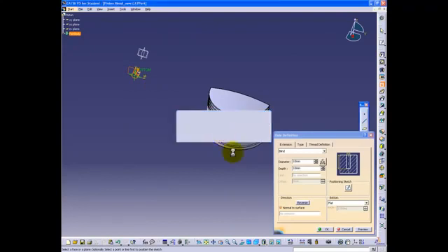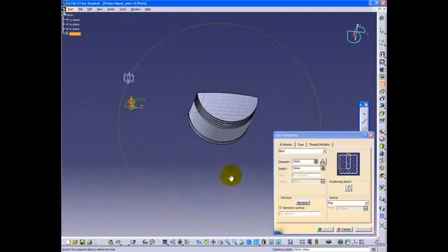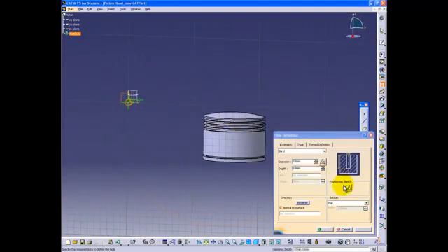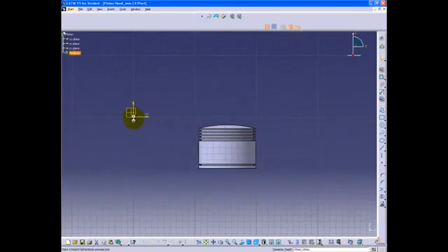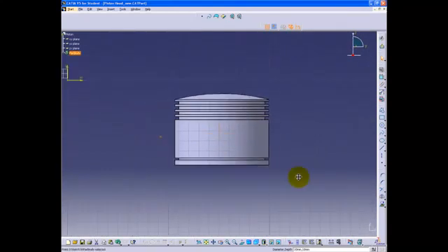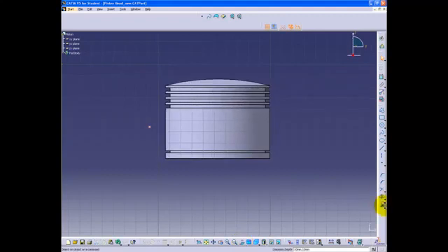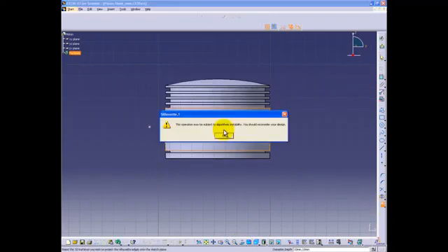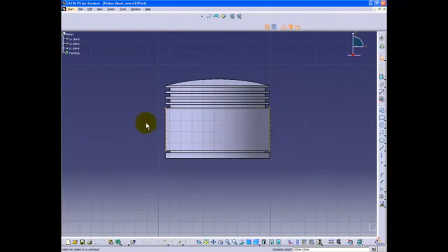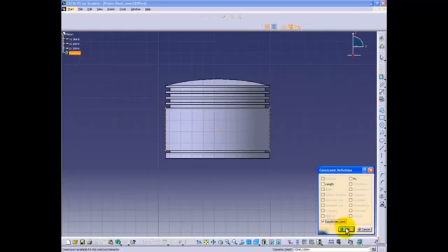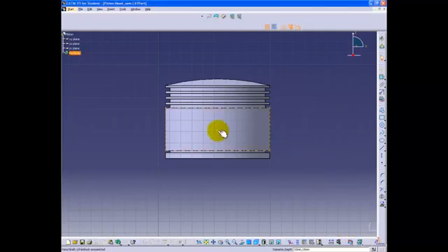To make a hole, you must select the hole command, and then the plane, and then go to the Position Sketch option. At this point, you should center the hole based on the dimensions that were given at the beginning of the section. Here we see the versatility of the Symmetry command when attempting to center the hole along the horizontal axis.